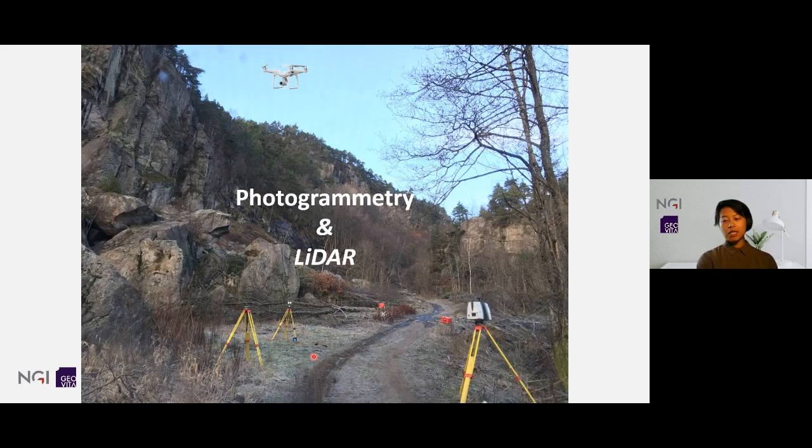There are 2 major techniques that are mainly used in obtaining 3D models of rock slopes in geosciences. One is photogrammetry, and the other is LiDAR scanning. We can use either of these to get 3D models, depending on the project size, locations and the environment. We can also use both to supplement each other. For example, one can use a LiDAR model to georeference the photogrammetry model, which makes use of the high accuracy of the positioning from the LiDAR model, but also full color from the photogrammetry model.